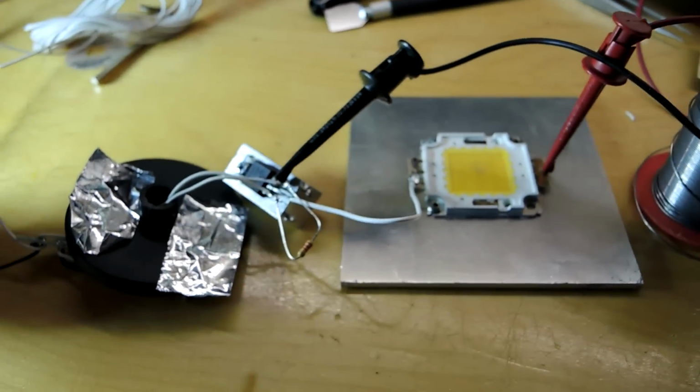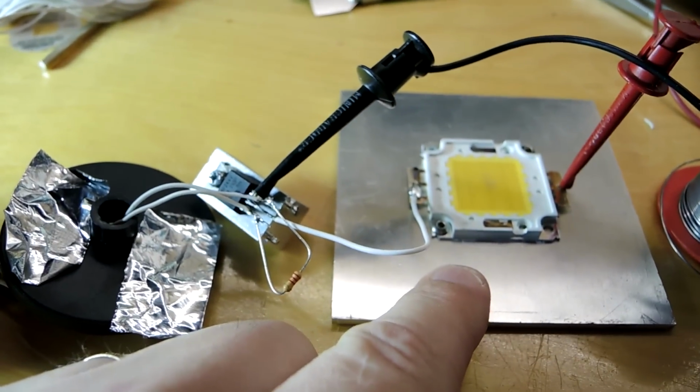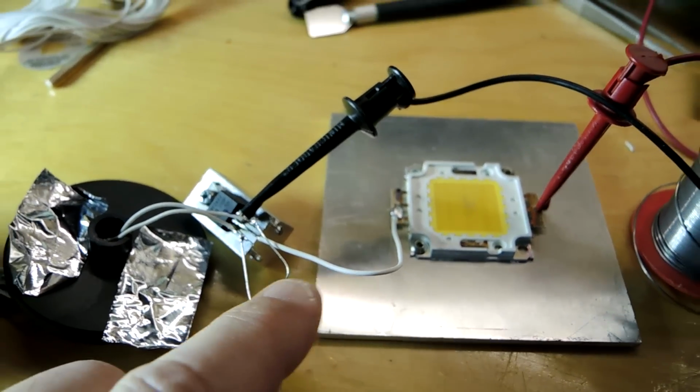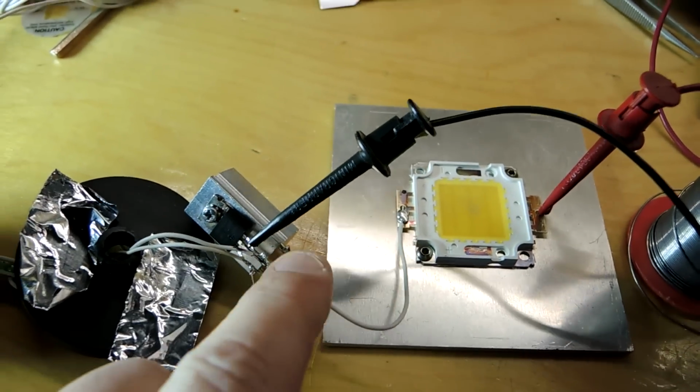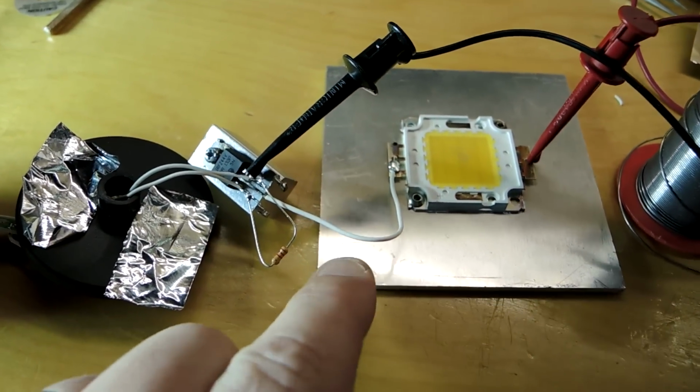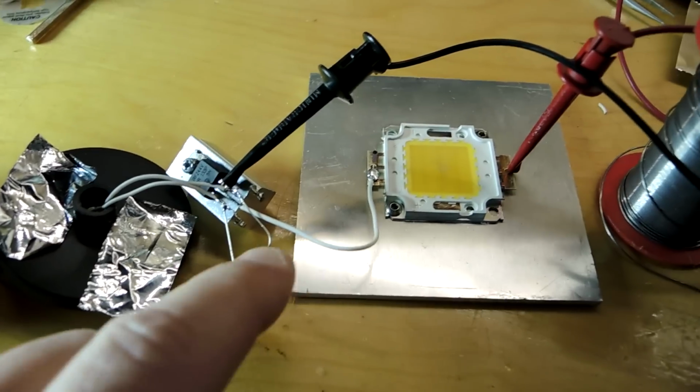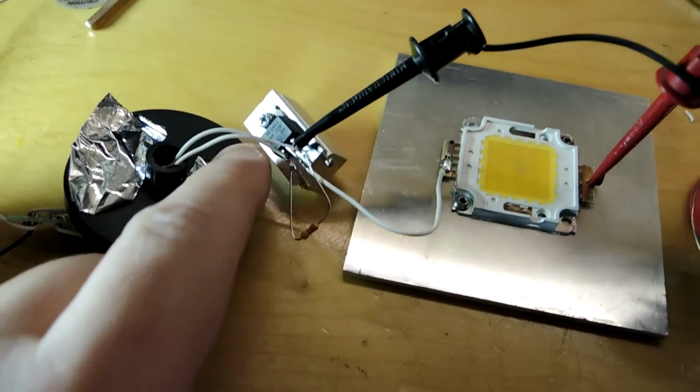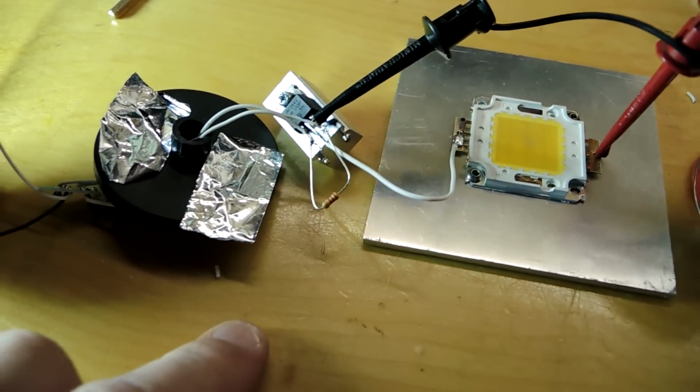I'll just turn it off because it's actually overwhelming the camera. And so yeah, not much else. Now there's of course some problems here. This really long lead wire, I suspect this thing will be spraying out a lot of RF energy as well. You want to have some snubbers. You don't want to drive like this with big long leads, but as a proof of concept, looking good.